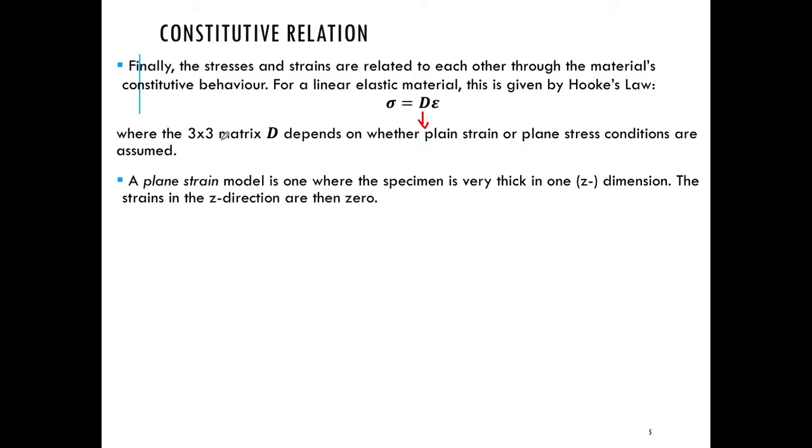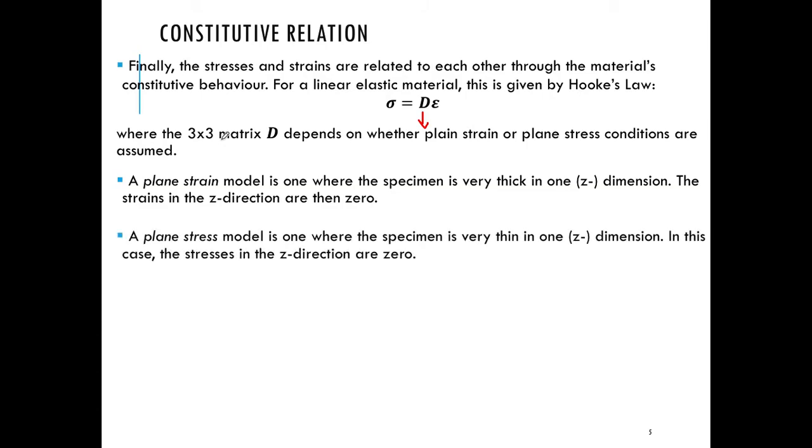That's plane strain, whereas conversely, plane stress is the case when we have very thin specimens such that we can assume that the stresses in one particular thin direction are all zero. That leads us to two different expressions for this D matrix, the material property matrix.